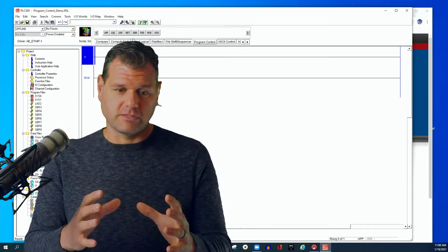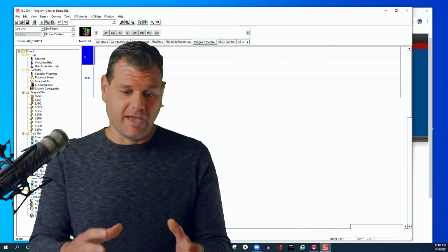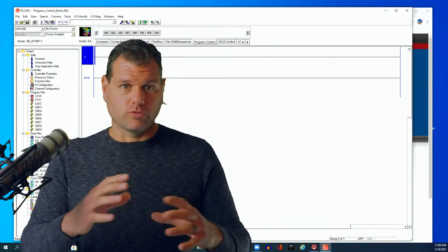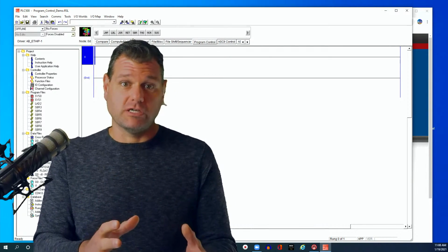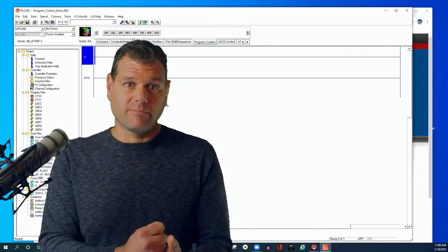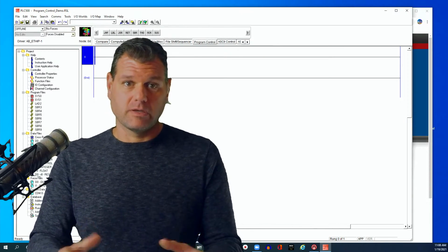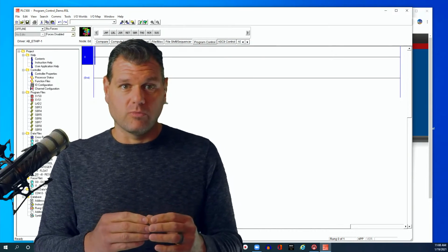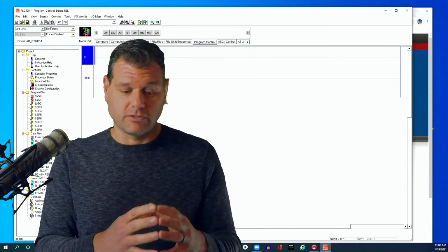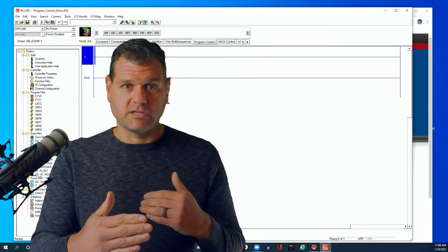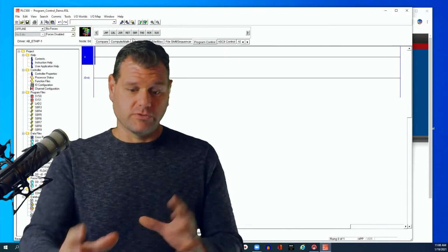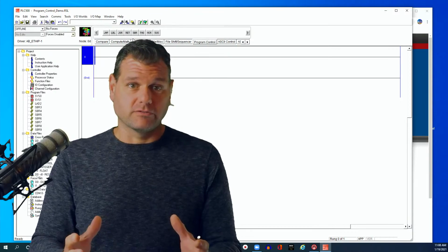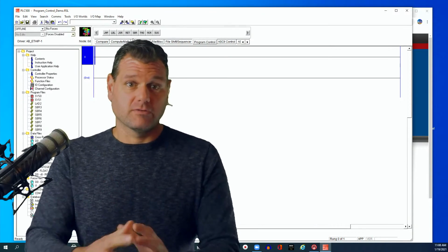So if something bad happens, let's say someone's getting their hand caught in a machine, or something's catching fire, you can hit an e-stop or some kind of stop system, and it will disable or pull apart the circuit with an electromagnetic switch, a contactor. Once that disconnects, we lose power to the entire system, or at least that part of it, and it just dies, right?